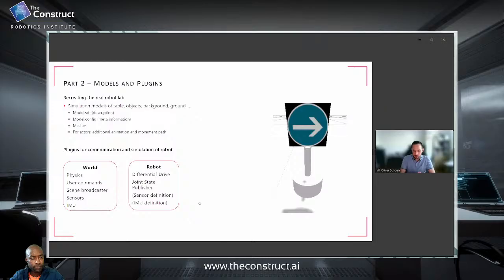Yes. And additionally, I put in here the sensor and IMU definition. So to say, the counterpart to the plugins of the world, we of course need to define the sensors and the IMU we are using in the robot, so that these parts are working together. So the sensor is working on the robot, but in the world file, we have the plugin that is basically providing the information then to the outside.